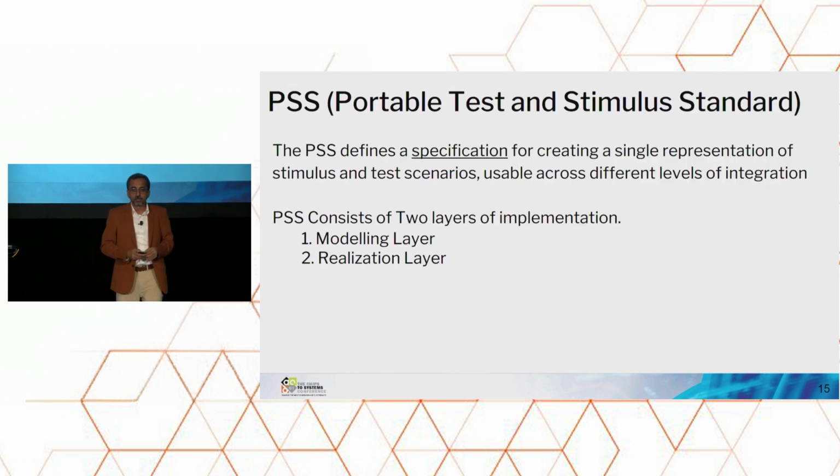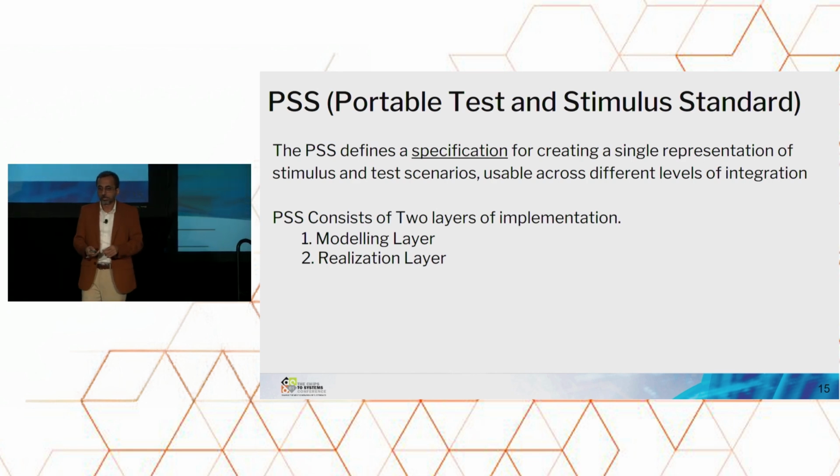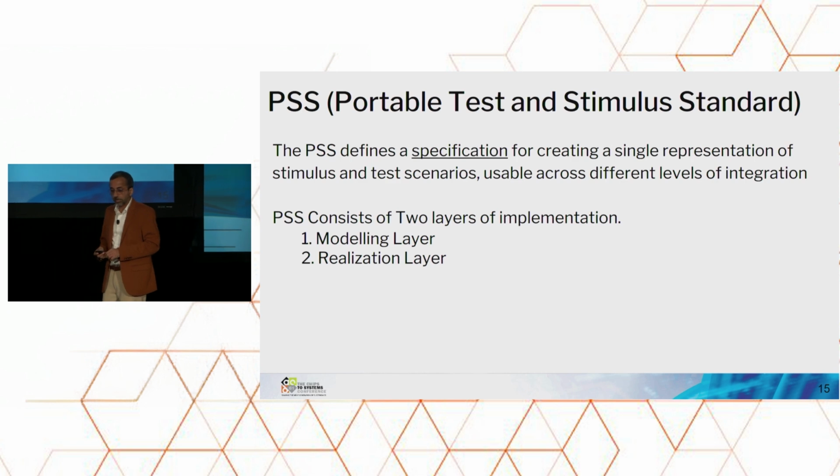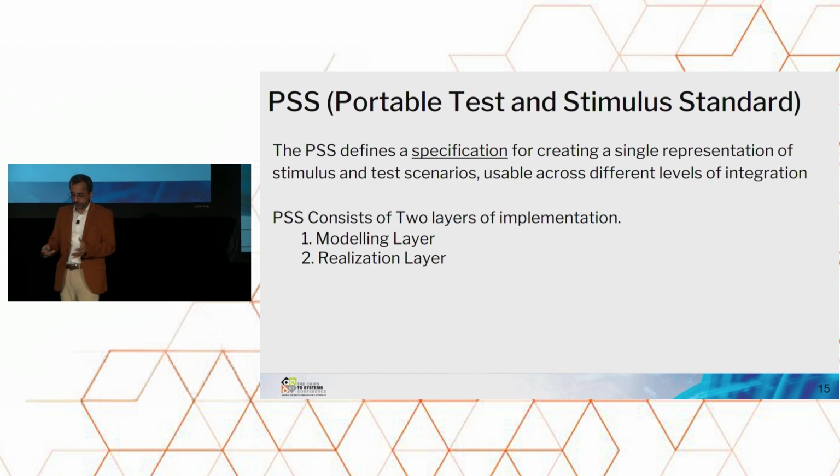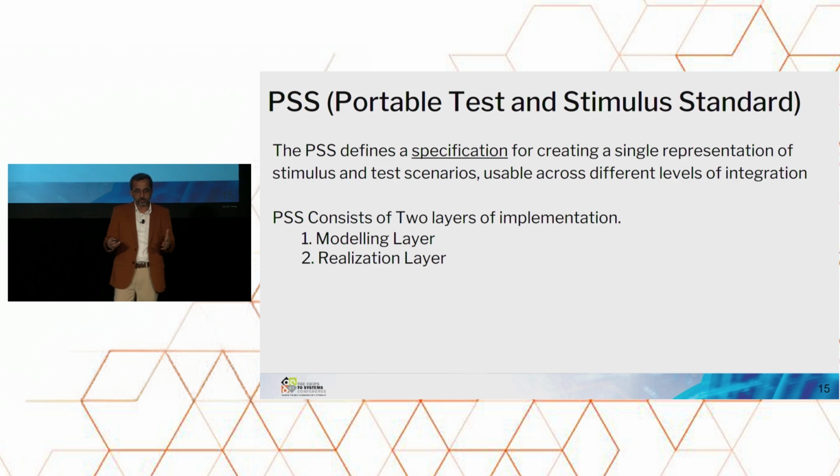Okay, the next slide. The PSS language is again a very recent innovation. Actually, now it's onto 3.0. Again, that's part of Accellera. Mostly it was designed for testing the hardware, like for multi-core hardware. Well, we're using it for programming it, at the IP level. The language is pretty elaborate. It has a modeling layer and a realization layer.